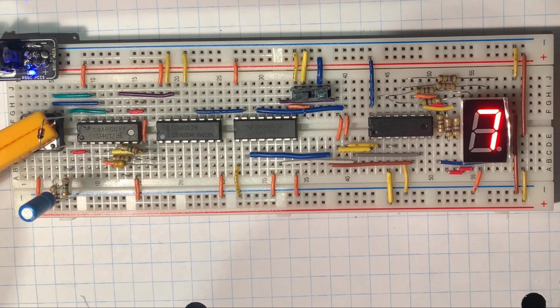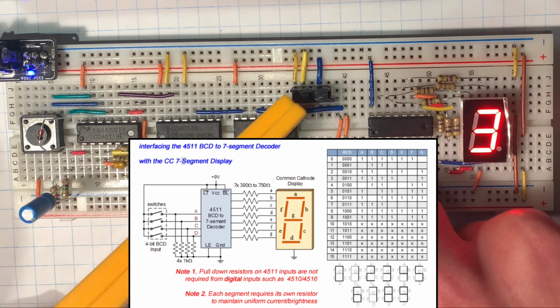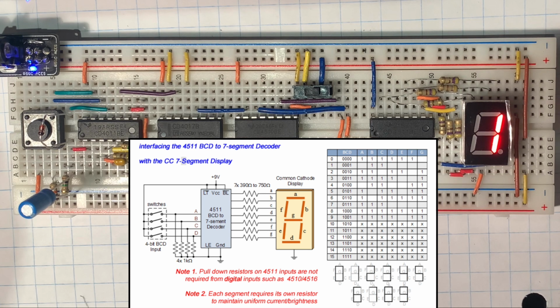display. In this image, the 4 switches represent the 4 binary outputs of the binary up and down counting chip. The 4511 chip then connects those outputs into their corresponding binary inputs. Then, the 7 outputs of this chip are connected to their corresponding inputs in the 7-segment display. Each time a binary number is produced, the 4511 chip converts it into a decimal number system counting output. The table on the right is a high-low table for each segment in the 7-segment display.